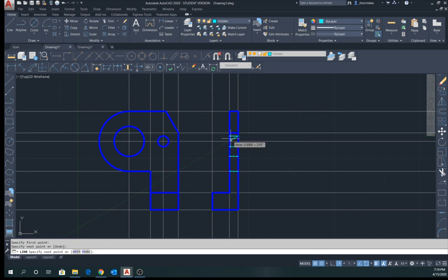Now remember, the way these drawings work is they don't give you a complete picture of the part. A single drawing doesn't. You have to look at both drawings to actually understand what's going on. So all these hidden lines, potentially that could mean there's one hole here and one hole here. This doesn't really tell you that there's actually two holes and they're both centered at the same location.